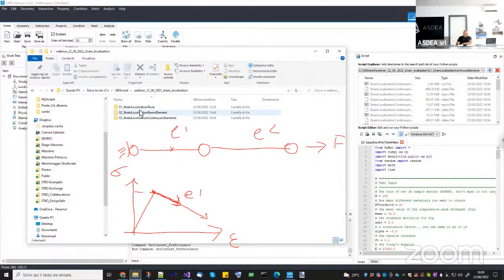Now, the problem is that when you are in strain hardening, there is no problem. Okay, imagine like this. So the first element goes here. It is here, element 1. The second element should be at the same stress, but there is only one point. So there is a uniqueness of the solution. When you have strain softening, there is not such a uniqueness of the solution, because for the same stress, the other element can be either loading like this, like the first element, or unloading, okay? Because both situations can give you the same stress. So it will be in equilibrium with the force here.